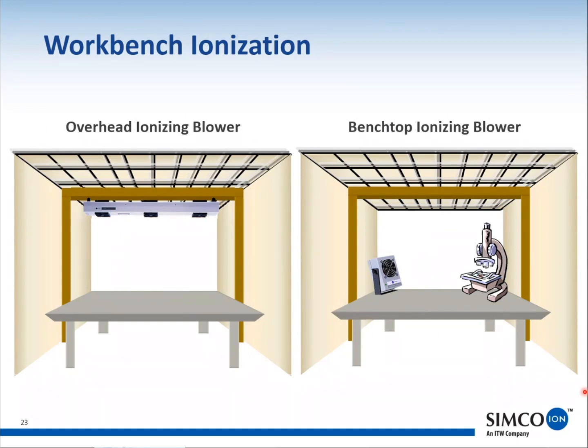Well, the ionization is basically, it'll take the charge off. If you're under it long enough. And as long as you don't touch that material again, it normally won't recharge. There has to be some form of charging mechanism on that material to charge it back up. So if you don't touch it, it likely won't recharge. But as soon as you touch it again, if you don't have ions present when you touch it again, it will recharge.